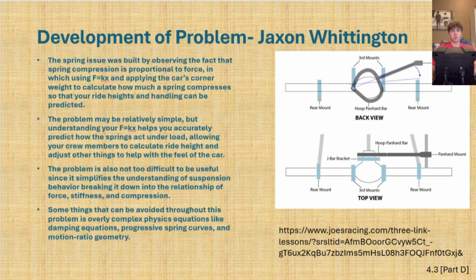The math is actually relatively simple, but it breaks it down into three categories between force, stiffness, and compression, and ultimately lets your entire crew more quickly tune the car to your likings without complicated physics like damping equations or motion ratio calculations.